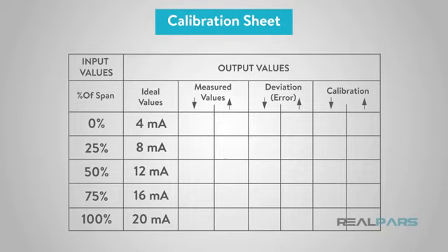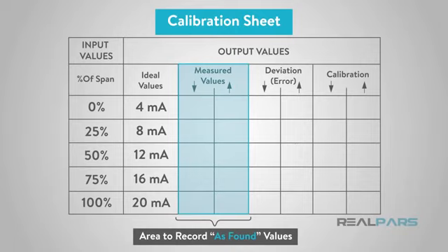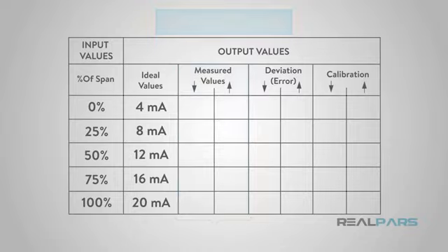In order to minimize the amount of time that it takes to perform a sensor calibration, I would first do an as-found check on the instrument. This is simply performing a calibration prior to making any adjustments. If the current instrument calibration is found to be within the stated tolerance for the device, then recalibration is not required.